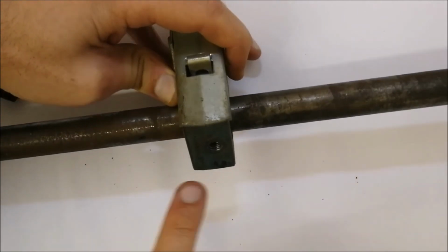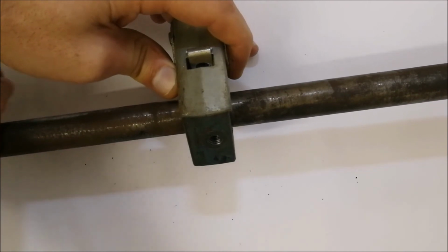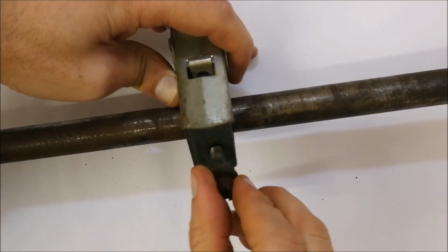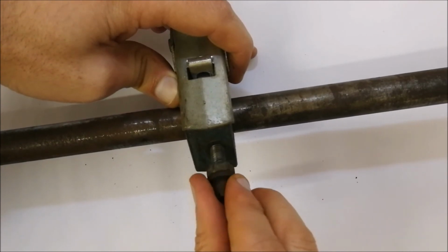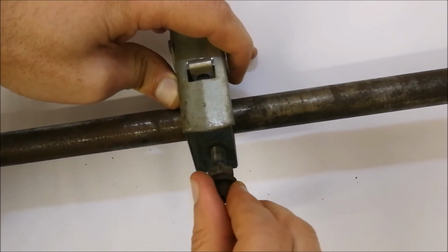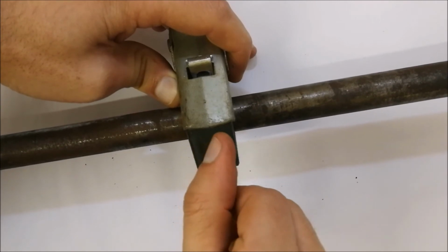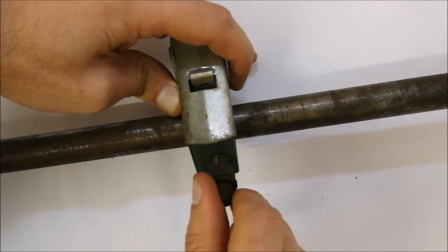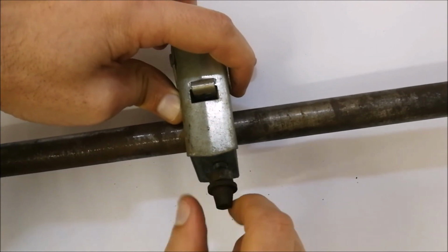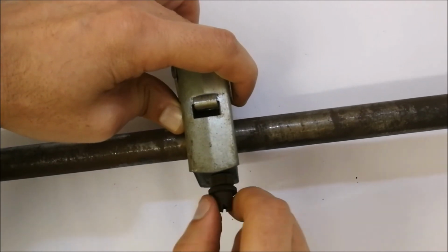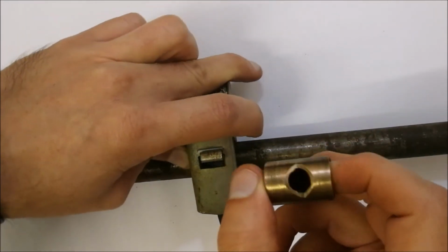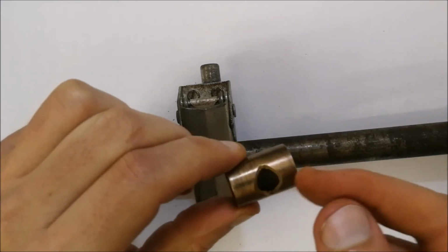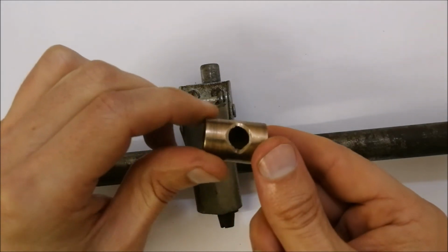You can place your grease in over there, and then you're able to lubricate that shaft by just closing this bolt and turning it every time you want a little bit more grease to go in and lubricate the system. So that is the reason why you would find that a bush such as this one would have a little hole in it, and that will allow the grease to go through to the shaft and lubricate the system.